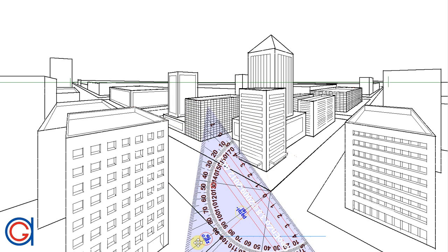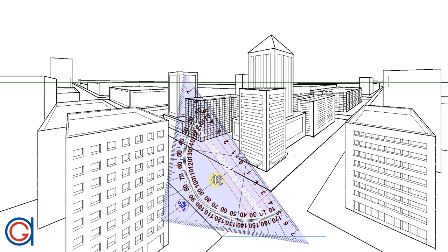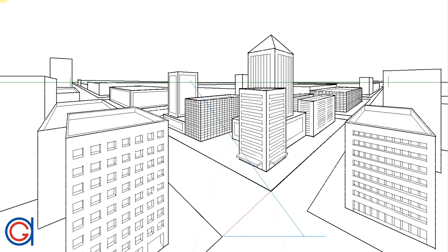Now, from the bottom of the red line, we draw a blue line at any angle you choose, and now we are going to divide this blue line into the amount of equal segments that we want on our zebra crossing. In order to find the vanishing point, we must join the last division of the blue line to the top part of the red line and extend this line until it cuts the green horizon line. Where it cuts it, this will be our vanishing point, as can be seen here. So the next step is to join all the previously made divisions on the blue line to this new vanishing point, as can be seen here.